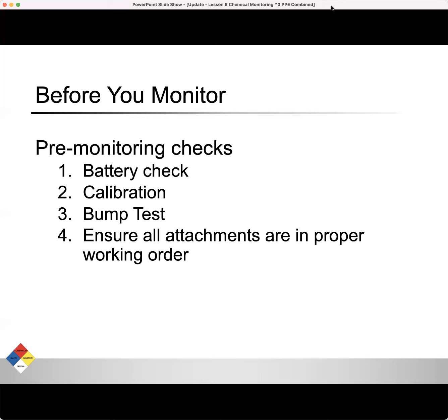The procedure is very similar to calibration, but you expose the monitor to your calibration gas and make sure that it will alarm at the readings that you expect it to alarm. You're just checking it to make sure that it's going to alarm when you need it to. That's a bump test.